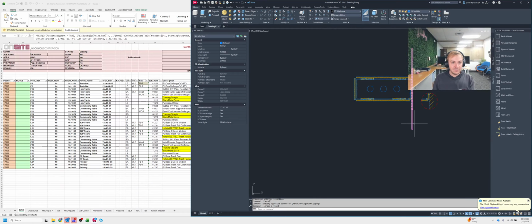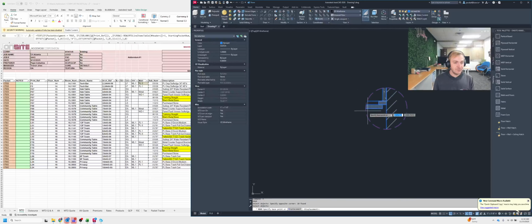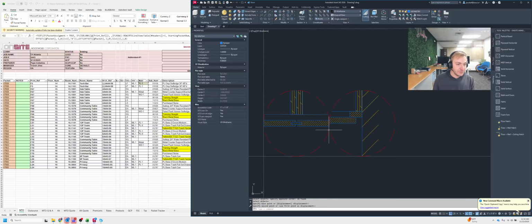So when you get to that corner, that is what that full depth reveal will look like. It's going to be a full depth block that sits behind the panel, and then your panel is going to stop short of the wall by 3/4 of an inch, just like this. Let's take this detail and move it down to here with our other views.